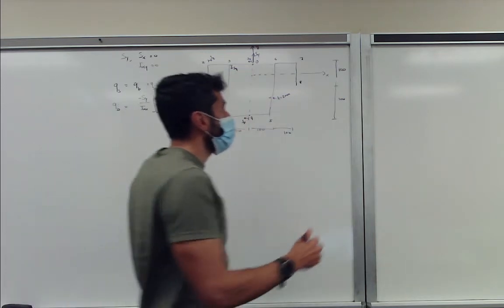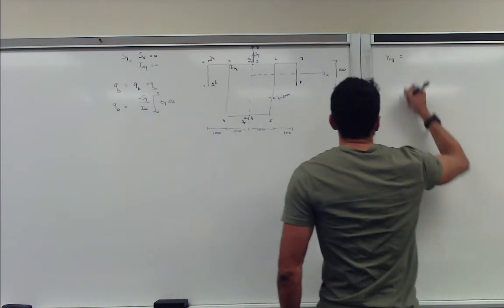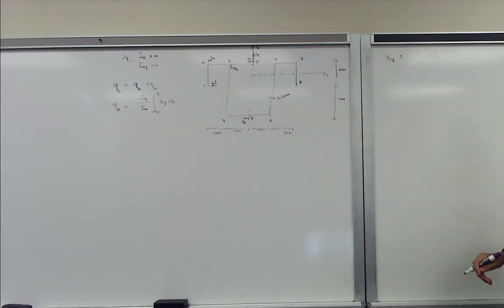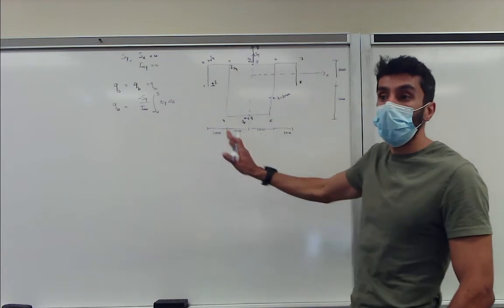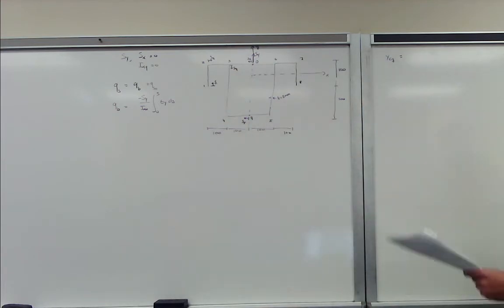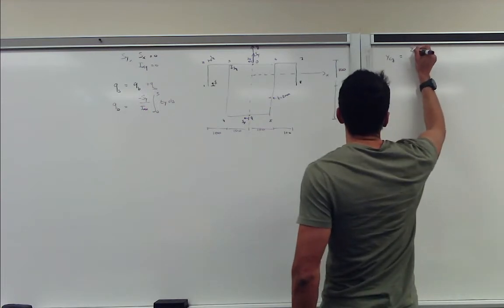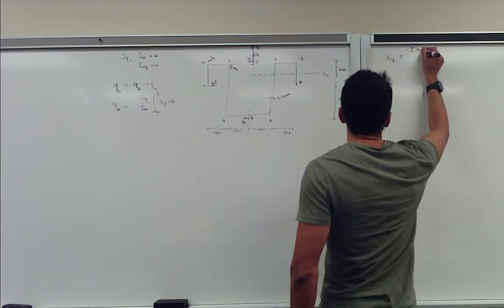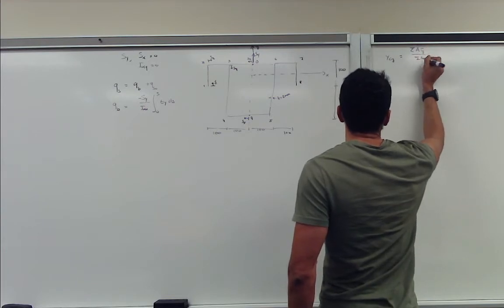So step one in this case would be calculating the y distance for the centroidal axis. We know the x distance will lie on the y-axis somewhere, because based on symmetry, we know that. So that's equal to the summation of area times y over the summation of areas.